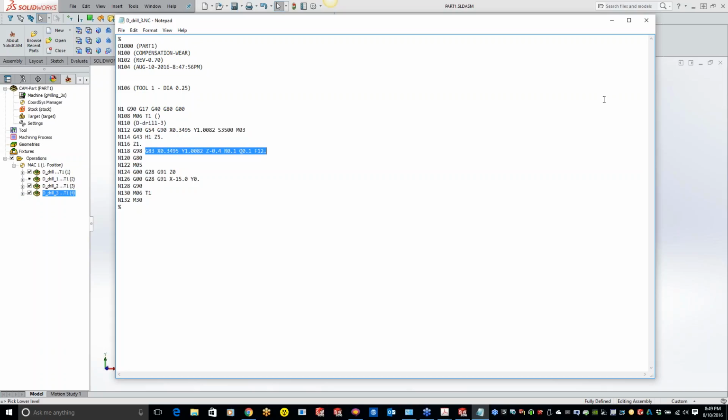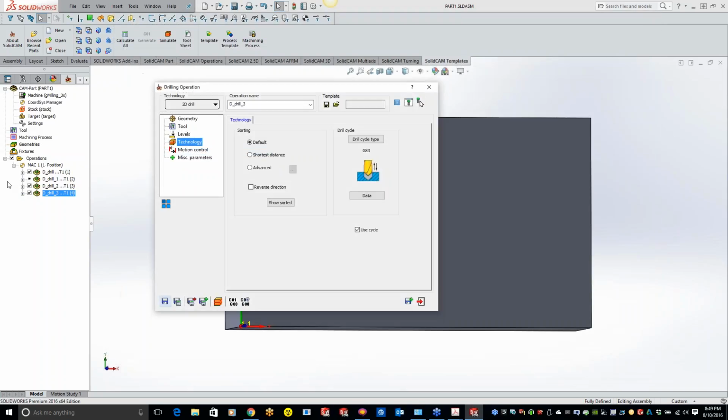And that's what we're actually doing here, just in this simple cycle right here, is basically everything that I just created here in these 5 operations. So like this one right here, we're going down 100 thou. This one here, we're going down 200 thou. This one, we're going down 300 thou. This one, we're going down 400 thou. So hopefully that kind of makes sense for you. And if not, let me know, or somebody let me know if I need to go into more.